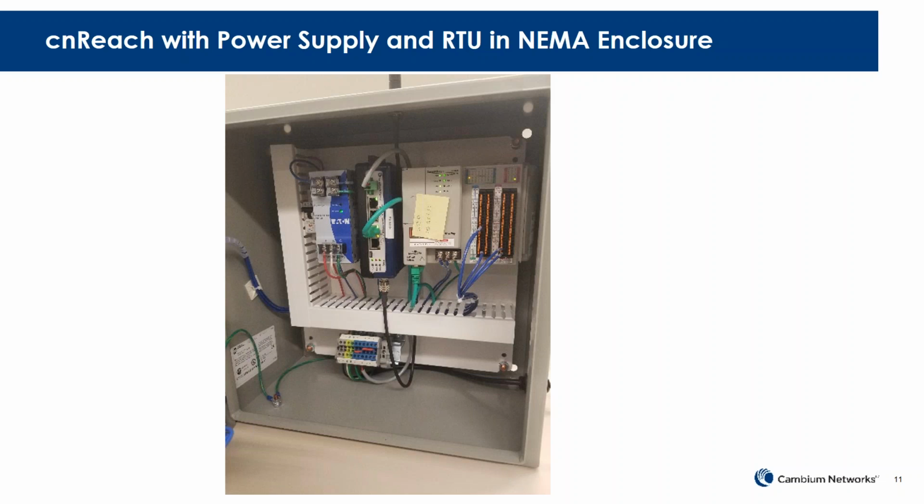So typically what you'll see in a cabinet like this is an RTU or a logic controller, a power source, and then a radio with the radio connecting up through an antenna out the top of the cabinet going up to either a Yagi or an Omni antenna configuration.